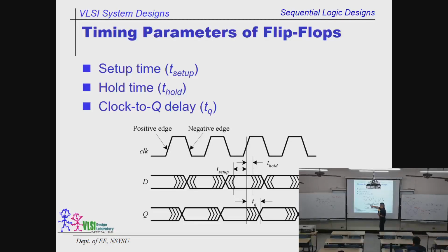This is D, and this means that the data could be drifted, because data could be high, could be low, and from time to time they could be switched, from high to low, something like that. And the switching time might be drifted. The drift in time is sometimes called jitter. Let me use this term so that you won't get confused.